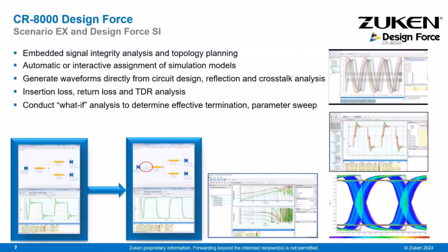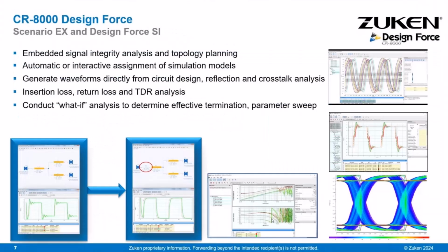Now, DesignForce also integrates powerful signal integrity analysis and topology planning features. It allows us to perform both automatic and interactive signal simulation. We can generate waveforms directly from the circuit design and perform important analysis like reflection and crosstalk, in addition to advanced analyses such as insertion loss, return loss, and TDR. As in Design Gateway, one of the most valuable features is the ability to conduct what-if analysis, and this lets us explore different design scenarios to optimize our design.